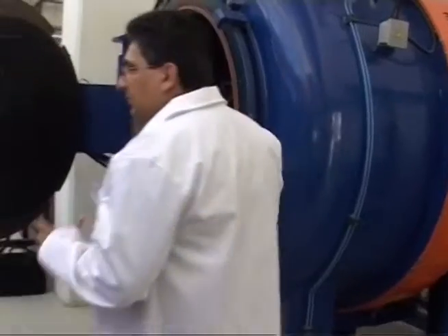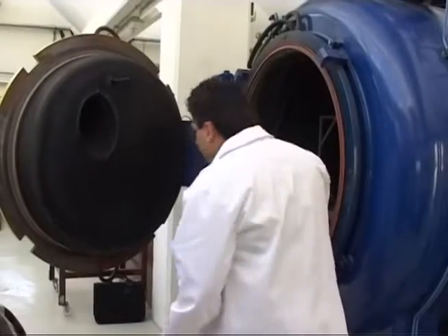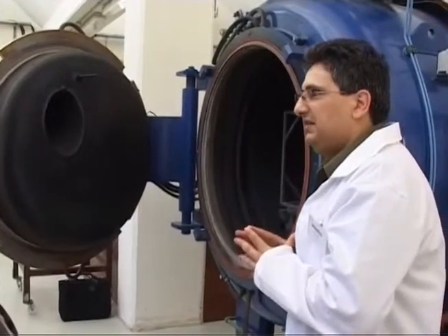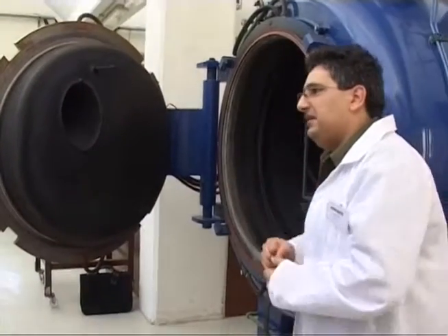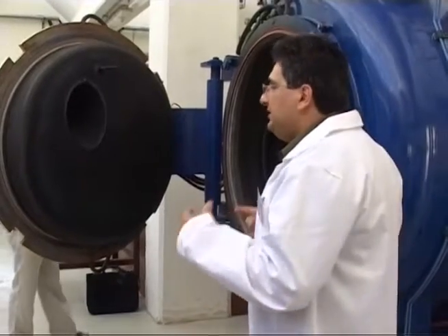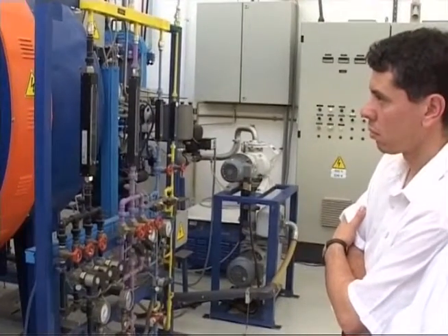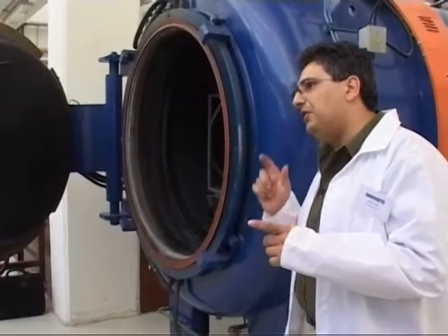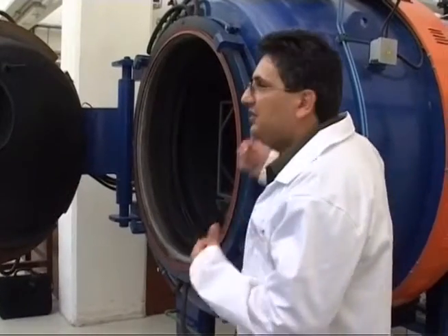When the furnace is operated in plasma mode, there is a third temperature control, and this is achieved by positioning the thermocouples inside the chamber close to a big and a small component, thereby controlling the different thermal capacity of the components inside and regulating the plasma power, which is an additional heat input inside the furnace. In this case, the target temperature is set 10 degrees below the operating temperature, and the excess 10 degrees is achieved by increasing the plasma power.